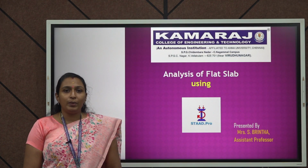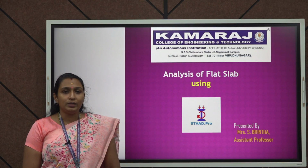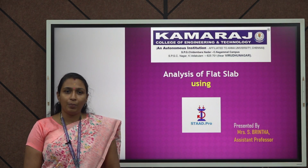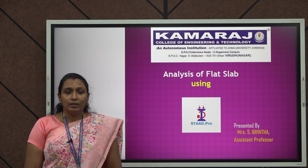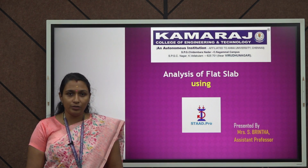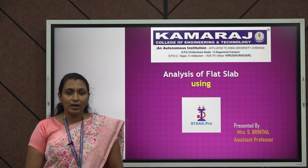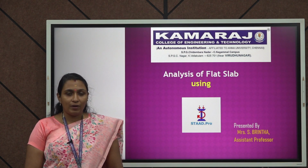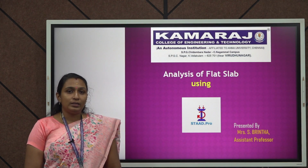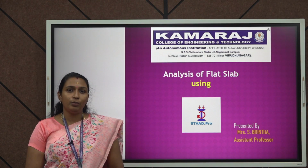The key difference between a two-way slab or one-way slab and the flat slab is that the flat slab is supported only on columns, not upon beams. There are a few types of flat slab, including flat slabs with drops, flat slabs with column head, and flat slabs with column head and drop. Let us see the basic analysis model of a flat slab without drop.